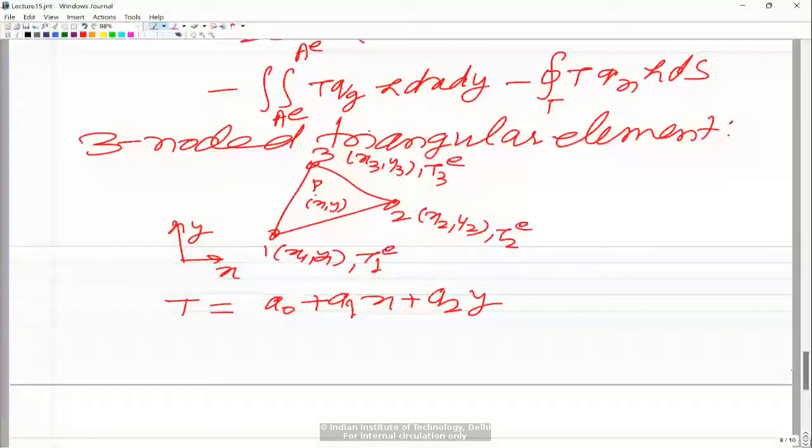So in this case the minimum polynomial a0 plus a1x plus a2y satisfies the differentiability requirement. That is, it is differentiable up to the highest order derivative present in the differential equation. It is a complete polynomial because we have constant, linear in x, and linear in y terms, and it is geometrically invariant because if we interchange x and y, the form doesn't change.